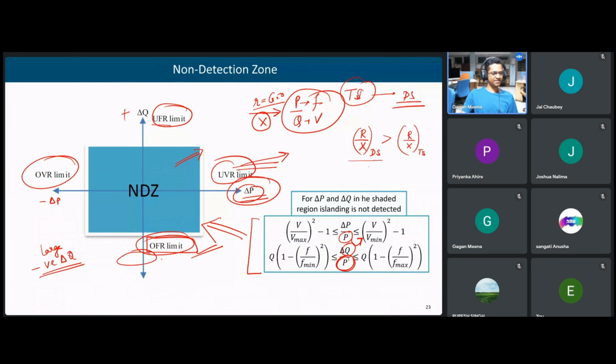So this R by X ratio in distribution system is much larger. And as a result of that, we are not able to decouple this. This decoupling is not possible. Because of that only we cannot use our conventional Gauss Seidel or Newton Raphson load flow methods, power flow methods. Because of this, all these things change. So is it clear?